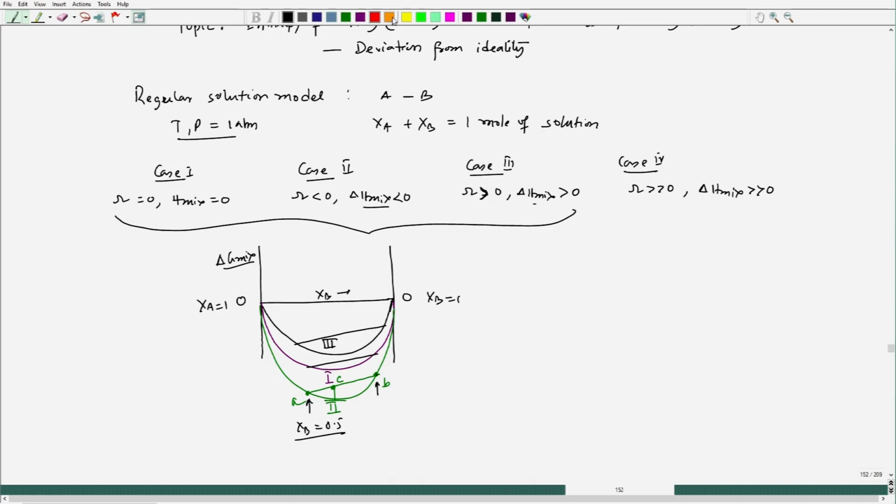Okay. So, for example, in this case the composition would be here, here it will be at this point. Like that way all those compositions will form. So, a homogeneous single phase solution would come out if we mix two different composition solutions because of the lowering of free energy. So, here you see the delta G is negative. Similarly, in all cases delta G is negative, here also delta G equal to negative. So, in all these cases they are spontaneous.